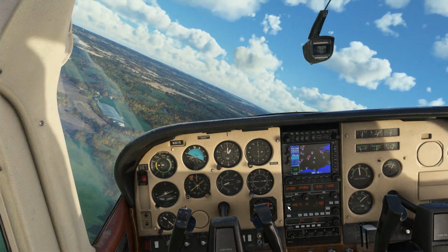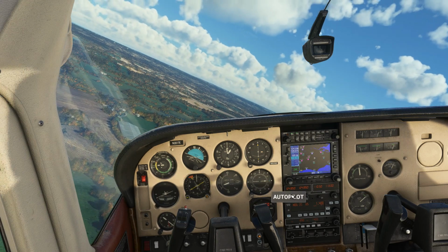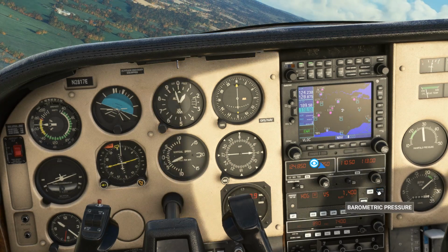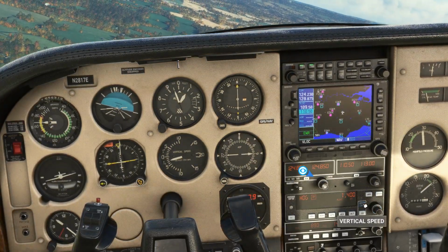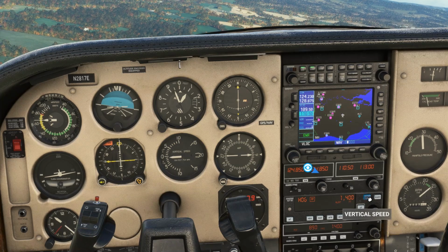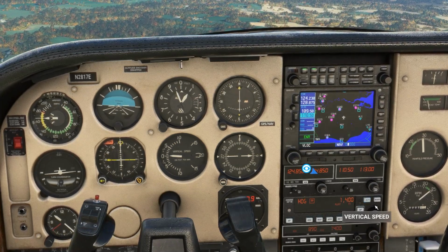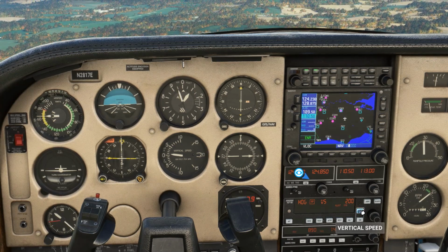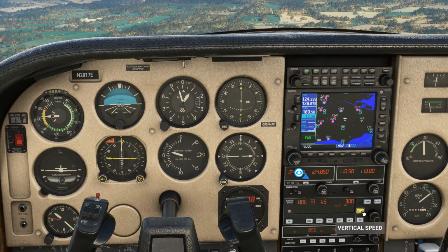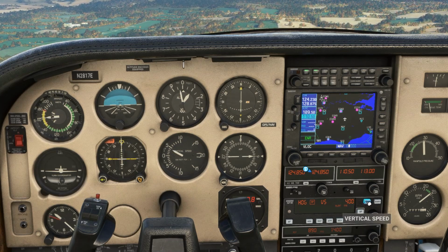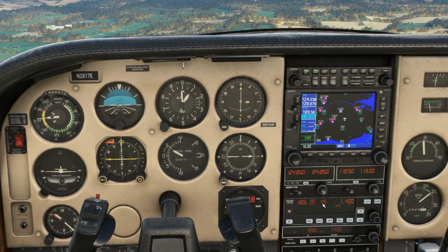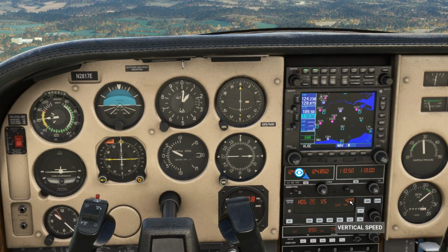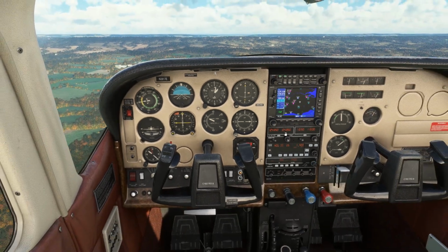Now, the aircraft is descending. You can see that. So I'm going to come down. I wasn't expecting that. I'm going to arm vertical speed, and I'm just going to push up. That's better. I'm going to push up on this button, the up or down, just so I climb at 400 feet per minute. So when you press arm there, make sure you got the vertical speed. VS stands for vertical speed. And now I'm climbing at 400 feet per minute, back up to 1400 feet.